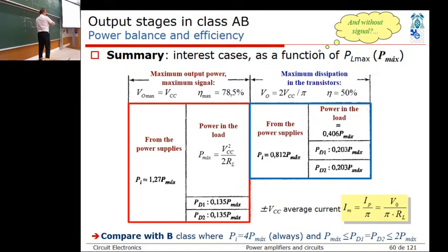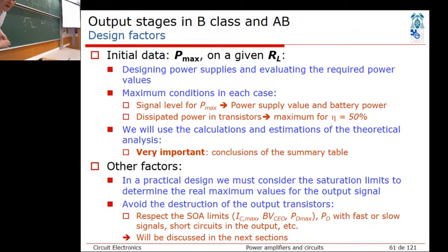You overdrive the pre-amplifier state, meaning that this actually becomes square wave. Ooh. Yep, that's when you get into deep trouble if you design it only with this theory based on sinusoidal signals. So engineering factor of 2 is okay. Okay. Good. Other factors?